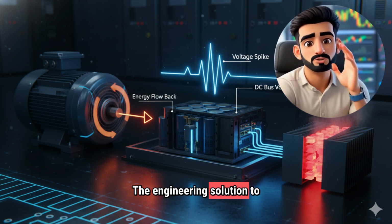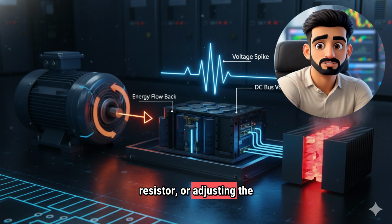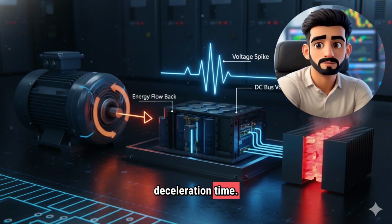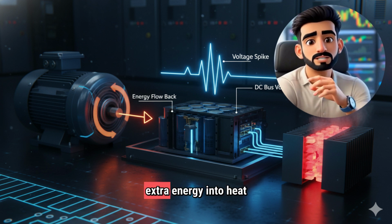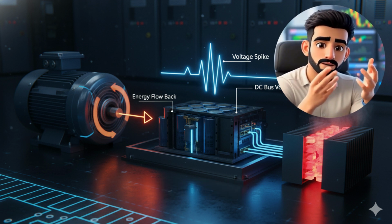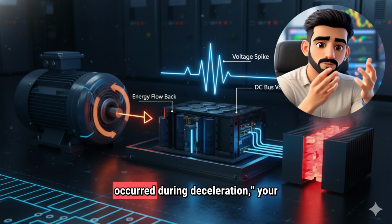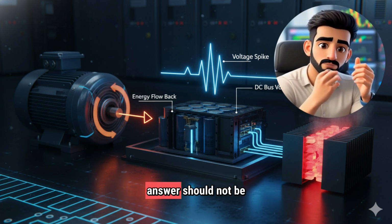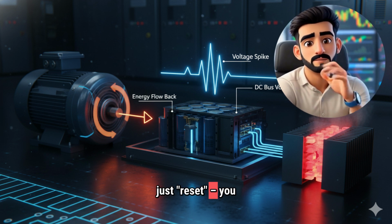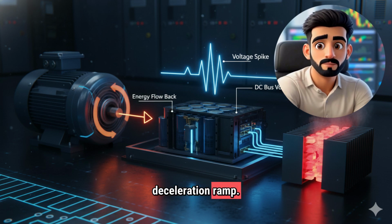The engineering solution to this problem is a braking chopper and braking resistor, or adjusting the deceleration time. The braking resistor converts extra energy into heat and keeps the DC bus within safe limits. If in an interview someone says, overvoltage fault occurred during deceleration, your answer should not be just reset. You should discuss both the braking system and the deceleration ramp.